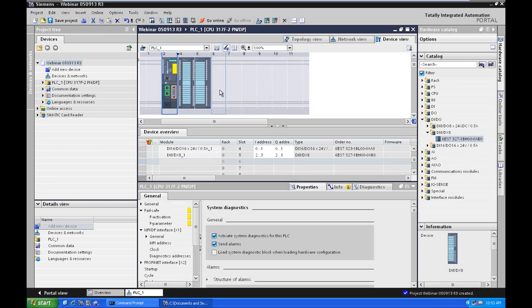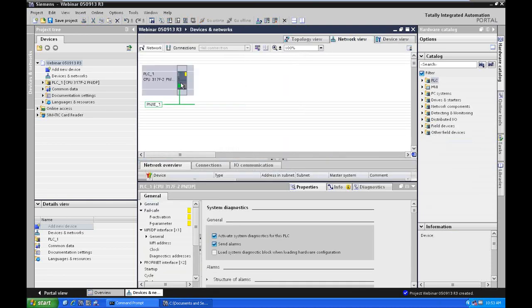I'm now going to add an ET200S node, which is our distributed I/O. And we have a couple of options on this CPU. We can distribute I/O over an Ethernet network, and that is our protocol with Siemens is Profinet. It's becoming an increasingly popular protocol among other manufacturers as well. So Profinet is the I/O protocol, and the PLC is the Profinet I/O controller. Every Profinet device will be an I/O device. Additionally, I could also distribute I/O via Profibus from the same processor. I have a Profinet I/O node configured here, so I will go ahead and add that node.